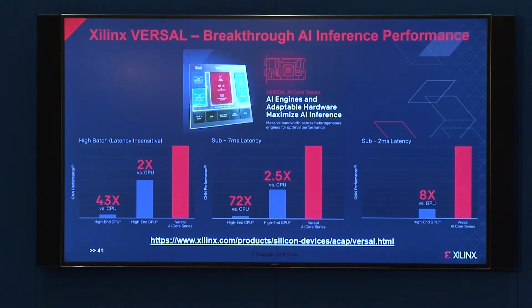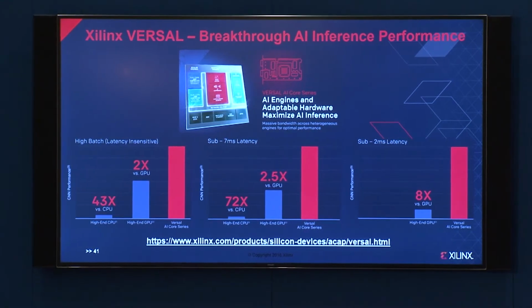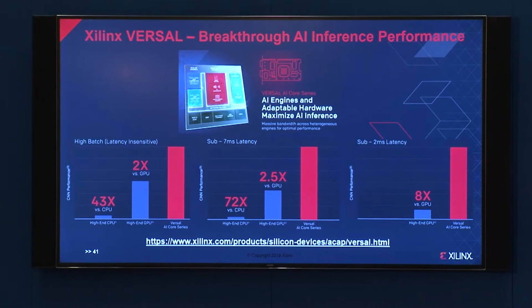This is our next generation of FPGA. Currently, our FPGAs are built with 16 nanometer. The next generation is built using 7 nanometer. And this overlay systolic array concept, what we did is we just went ahead and hardened it. So today, if you look at our Versal chips, the biggest chip, which will come out sometime next year, will have 110 teraops of int8 performance.